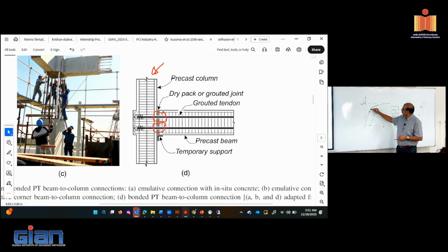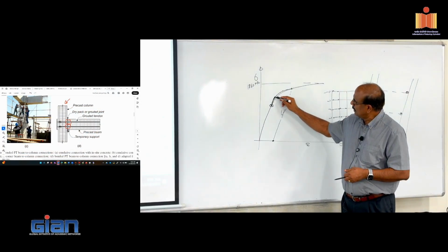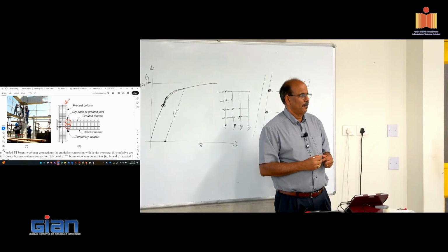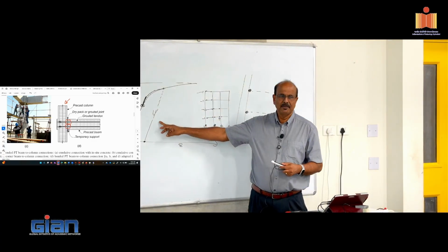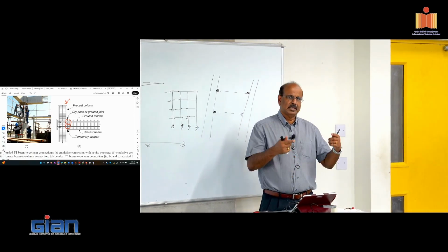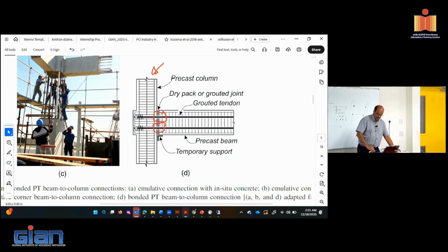Maybe it's going to go from here to here somewhere. So when you unload it, it doesn't lose that pre-stressing as you would if it's a perfectly bonded connection. So that was the reason they were able to convince themselves it seemed to work fine, but they're basically locally debonding the connection, and that's the reason it was surviving.